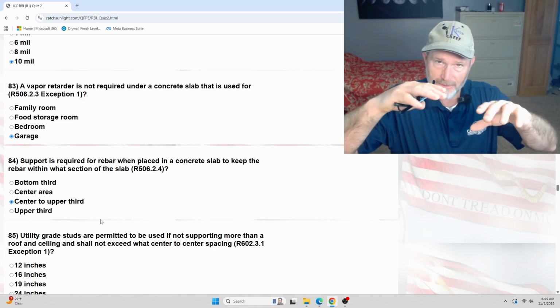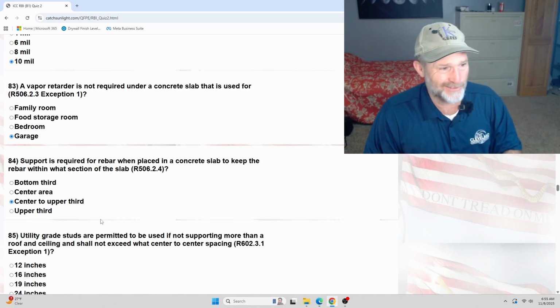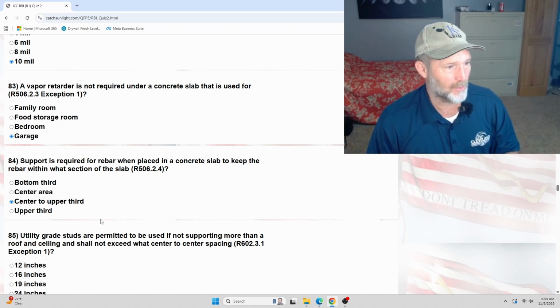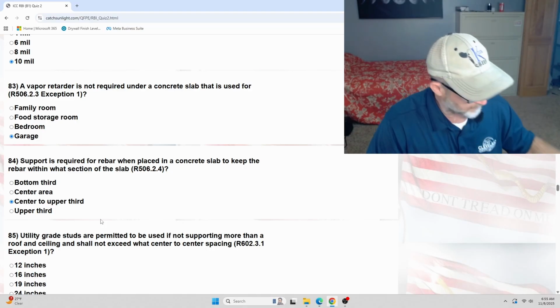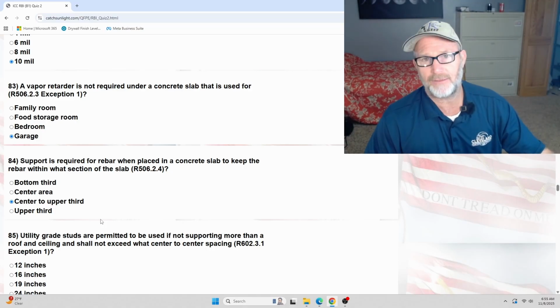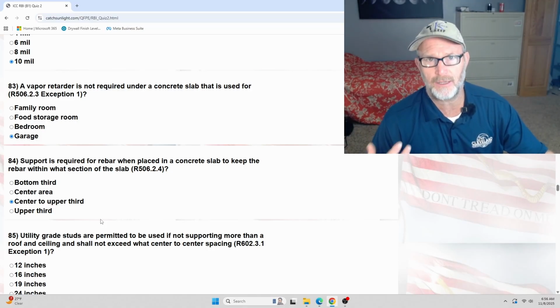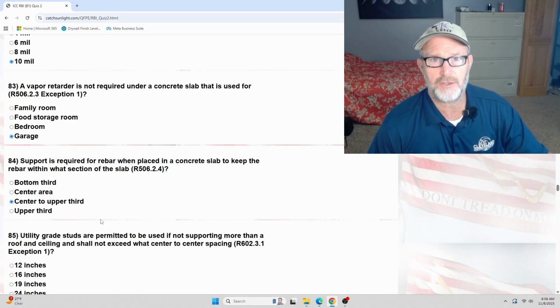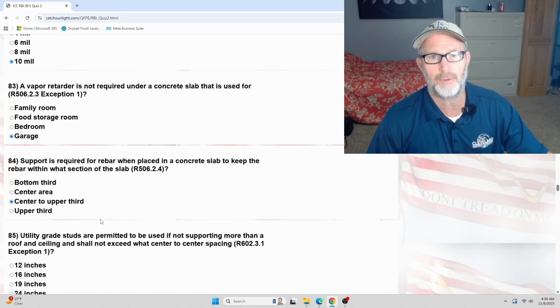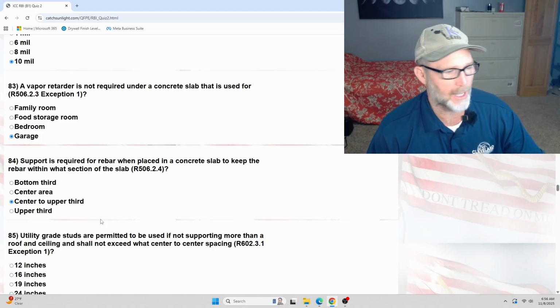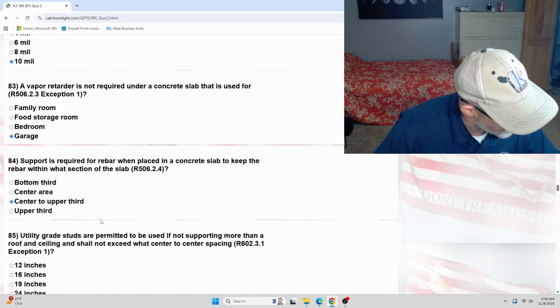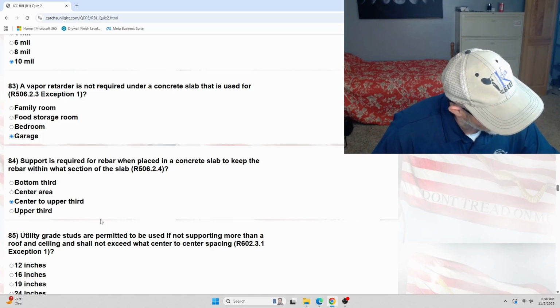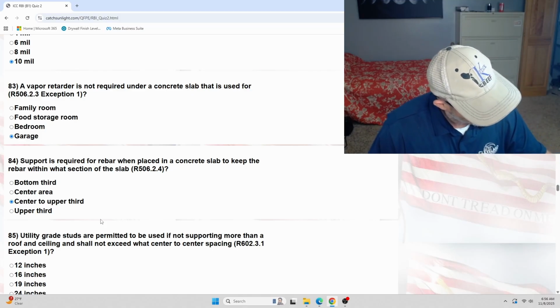But if you're up on the top part, which I would think I'd probably want more on the bottom part, I don't know why they have it on the top part here, but in any event, that's the member that would feel the stress. If it's in the neutral axis right in the middle, bad. You can't do that. If it's too close to the top or bottom, it's going to spall out. So that's why they spec these things out. But it is kind of interesting the way this is worded. I don't know if I would have done that.